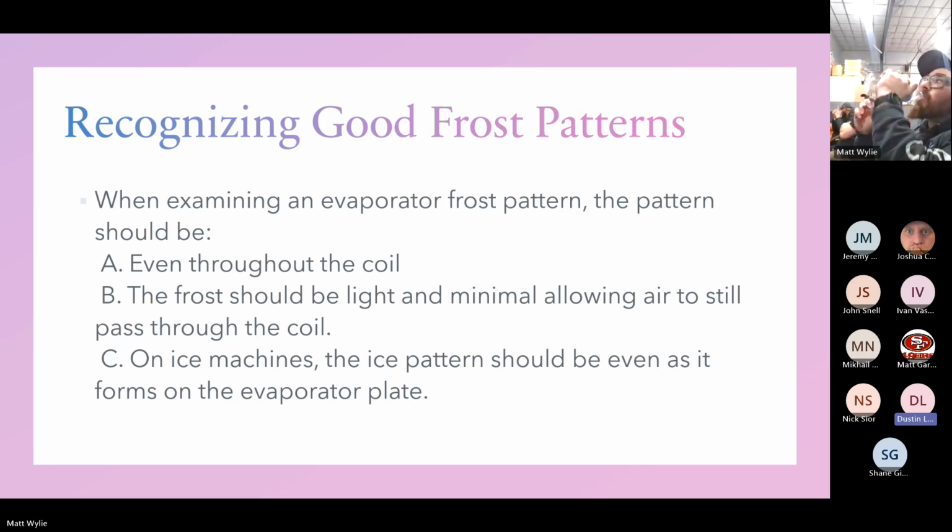A lot of times frost correlates to flood back. A lot of people see heavy frost on a suction line and think flood back. Don't just assume that it's flood back. Always verify by checking your superheat, because frost accumulates from a lot of other things too. Your suction line's cold, you're in an old grocery store, the insulation's all peeled off, and if it's humid in the store, that's going to accumulate more frost. So if you ever have a frosted up suction line, still always verify your superheat. Don't just go right to turning your expansion valve in and assuming it's flood back.